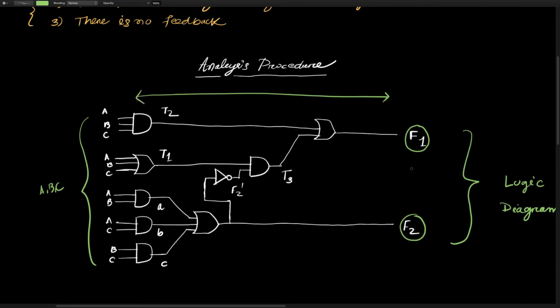It has output, input, and logic circuits in between, but there is no feedback or memory storage element. Among logic gates, we have different types of circuits that can store bits of data, and we call those memory elements, but in this particular example there are no such elements and there is no feedback also.